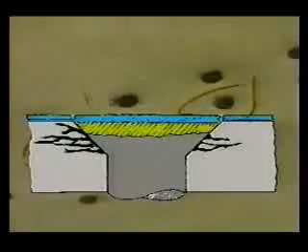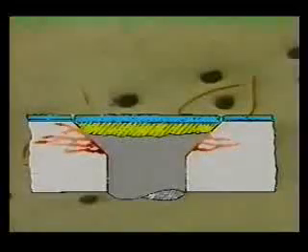This corrosion was caused by a breakdown in the paint film that shielded the metal from the environment. When the paint cracked, an electrolyte was allowed to enter the area and set up a corrosion cell between the steel fastener and aluminum skin. Whenever cracks or breaks in the painting system are discovered, they must be touched up as soon as possible to prevent corrosion.